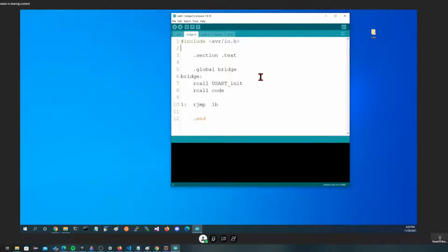Well, what is this going to do? Well, it's going to create a section called text. Now, text means to the assembler and linker that this section consists of executable instructions, and in our machine should be put into the flash on the computer. We'll see other sections in some other example programs we look at. But text means this is program code, meaning it's going to have instructions in it, and we should put this in flash.